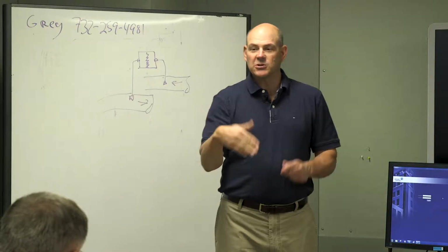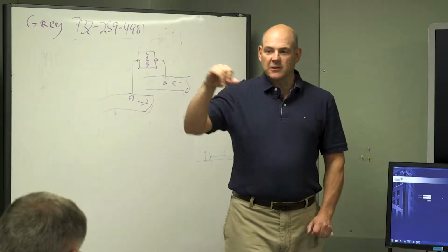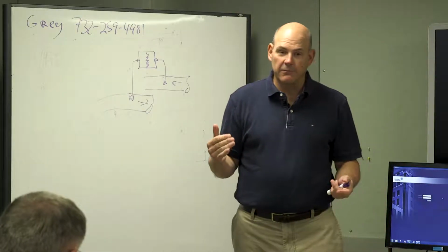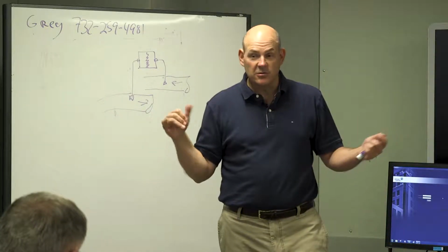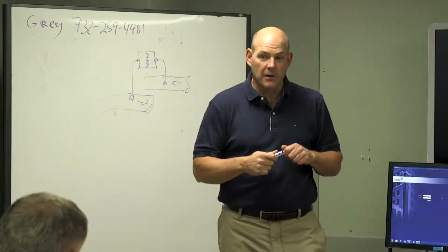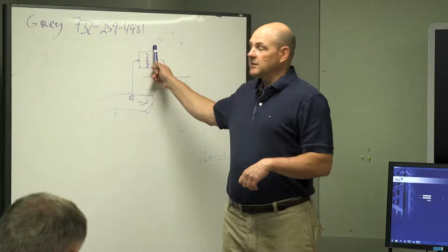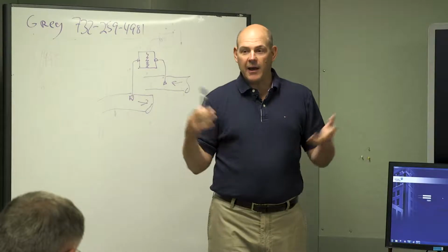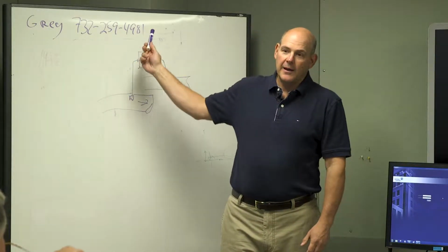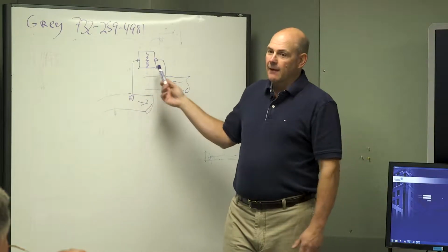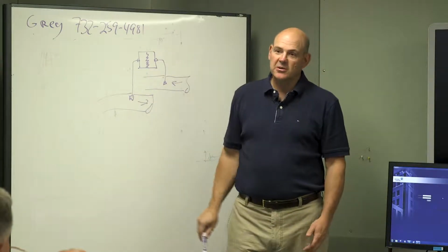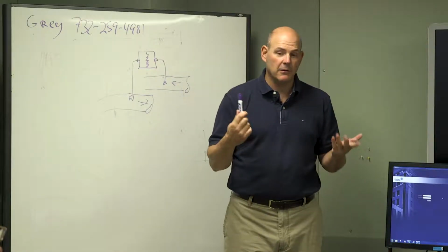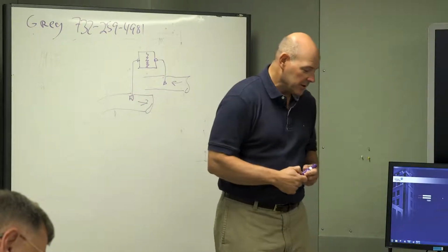So when you bring up the question, what's your minimum? You can use that device, look on the screen, say I don't have my minimum. Or you can look at the valves. The valves are the number one thing. If valves are closed, the chiller is going to trip because it doesn't have enough flow. If this starts to decrease during operation, you can start looking at your strainers. If you come in every day and the DP says 4.3 and the gallons per minute are X, and you keep running that chiller and this number starts to drop a little bit, there's either an issue with your pump, an issue with the strainer, impeller, something's clogged. It's a good maintenance point to check out.